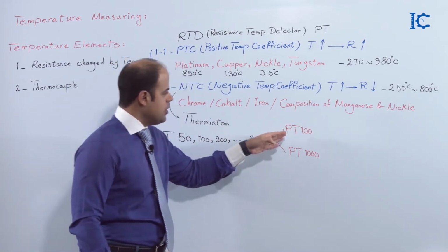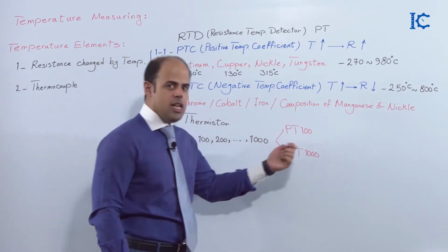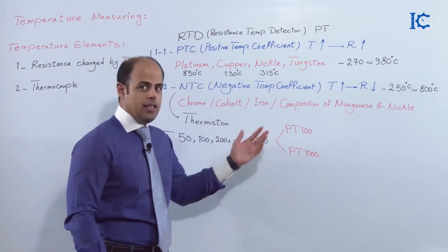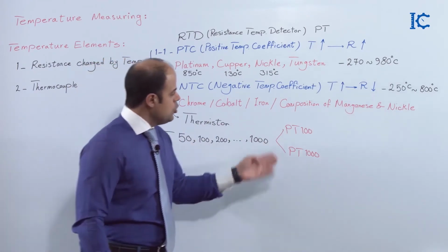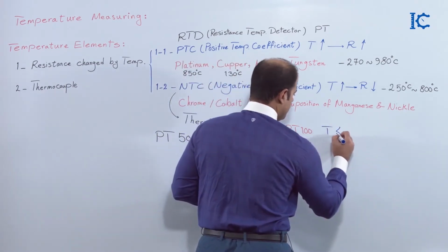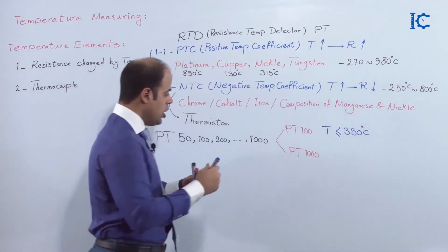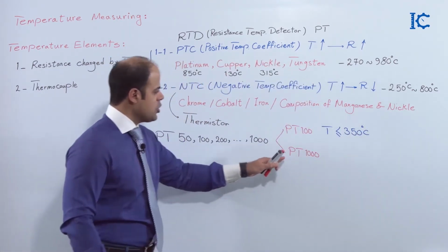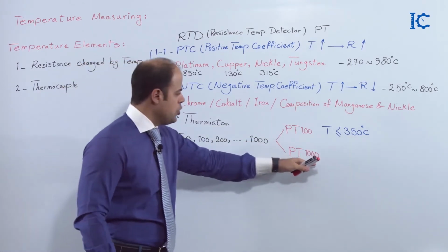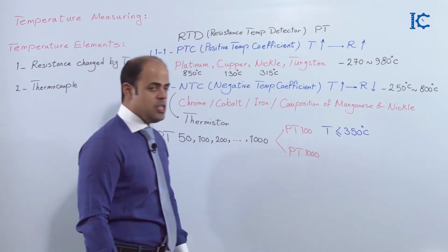So I can tell you that the prediction of the possible changes in the foreseeable future for this device is carried out better than for other items. So do not forget, for temperature less than this amount, try to use PT 100, and PT 1000 you can even use for more ranges too. For example, up to 700 or even 800 degrees centigrade, we can just use PT 1000.